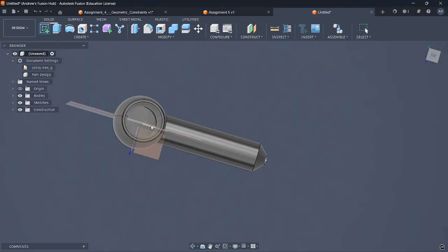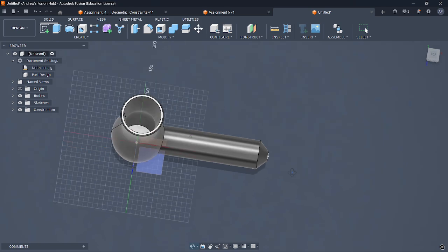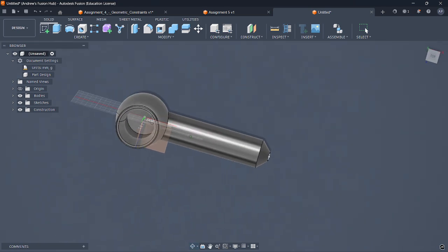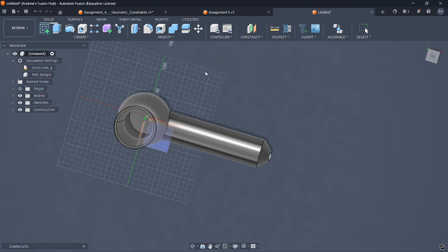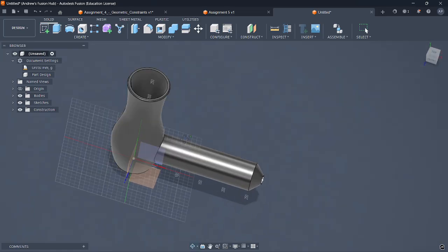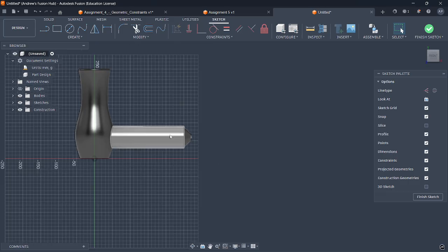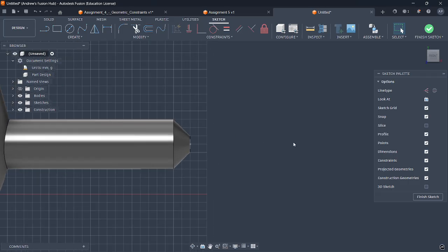In this case, this plane goes straight through the middle of this hairdryer, which is what we want. If you drew your circle way over here, then you'd have to create more planes, and that's kind of a pain. So again, you can do things off the origin, but sometimes it's a lot easier to not do that.